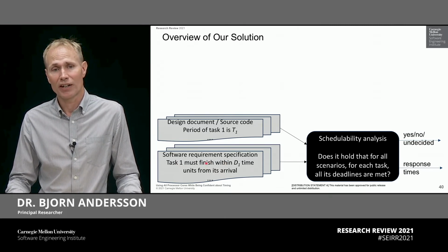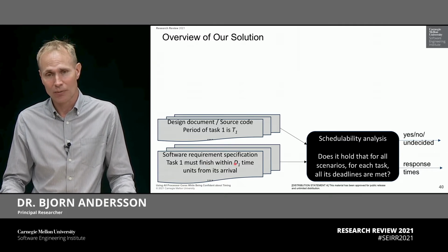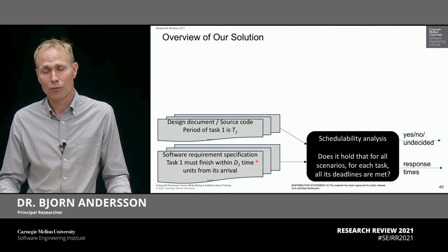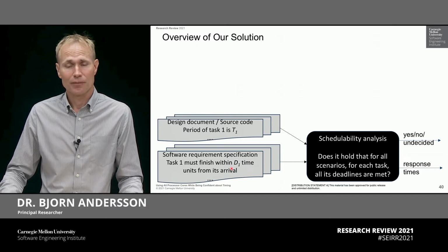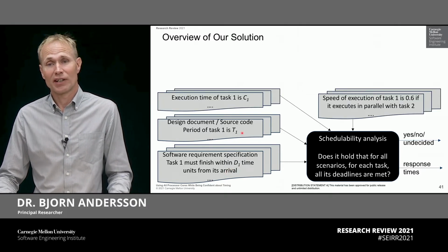We do not require that the deadline be equal to the period. We allow you to specify a deadline to be any value less than or equal to the period. So if you have a very tight deadline but a long period, from our perspective, it's fine if you write that down. We can analyze that. We need other things as input to the scalability analysis.